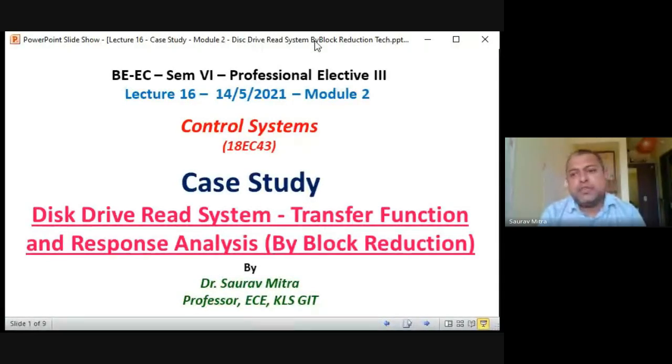And the main application of the DC series motor is for lifting purposes. So whenever there is a crane, a hoist, or a lift, a sudden jerk is required at the starting. It's a kind of an impulse function. Whenever these kinds of applications are there, that is, initially in just one pull I have to lift something, there the DC series motor is applied, because the DC series motor has a very high starting torque. That is the first thing.